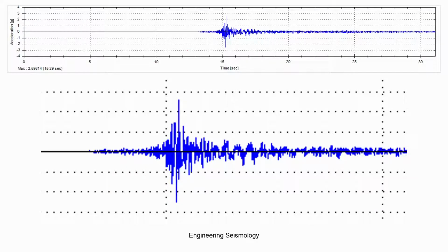As we have shown, this is typically one component of the acceleration time record. You can see that this is actually an extracted portion of the entire record, and that the record is dominated at this place. Predominantly this is the P wave, and somewhere here the S wave will be there. If you zoom in, you can see the strength of the earthquake lies somewhere here. These portions impart more energy to the structure. So we need to deal with this in a proper and systematic manner. That is what we do in the frequency domain analysis, where we estimate the frequency domain parameters.